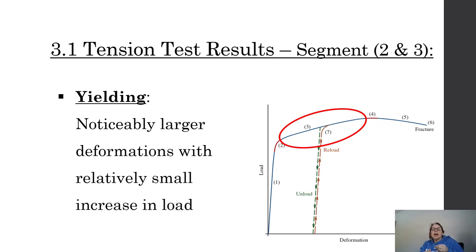So we apply this tensile force until we get to a certain point, the end of the elastic region, before we move to permanent deformation. And now I don't have to apply load anymore. I can almost keep that load constant, but deformation is occurring. I want you to think about silly putty, because silly putty is one of those materials that's pretty easy to see. Think back to your childhood and stretching the silly putty.